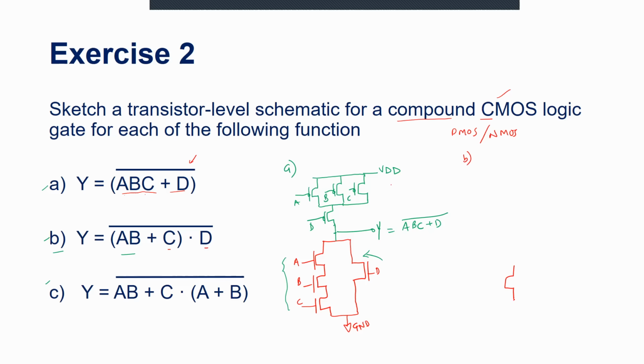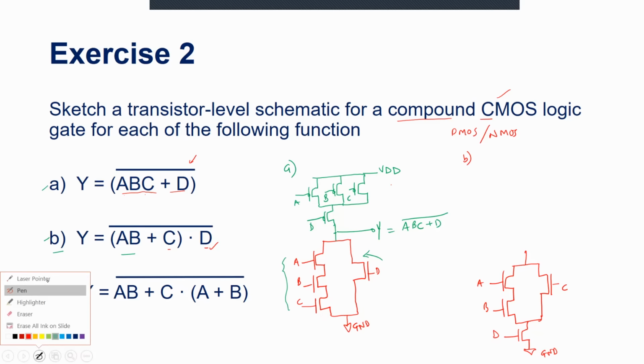So I have these 2 switches, A and B. It is forming an ORing in parallel with another input, that is C. But I have another input, D, which is in ANDing with this. So I draw another switch here with the input D, and that's ground potential right here. Once I do that, I now have to take the complement of it.